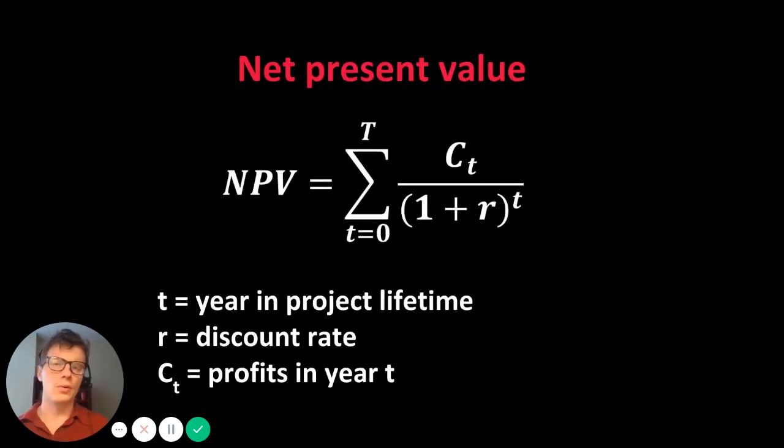If we wanted to look at a more nuanced metric for deciding what type of power plant to build, we might look at net present value, especially if we're talking about a generation company that's participating in a competitive market for electricity, because they don't necessarily want to just look at costs. They also want to look at their ability to make profits. And they could discount those profits out into the future based on some sort of expectation. And compare different types of power plants alongside one another, while choosing the one with the highest net present value as the most optimal choice.